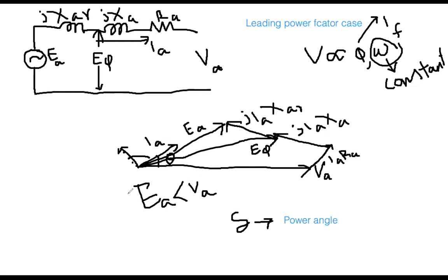So, what is that EA? EA is that internal voltage. And what is the factor? Again, the flux. I am assuming speed is constant. So the main thing is the flux. This means because EA is much less than the VA, the generator needs to produce a small voltage with the expense of a small flux. So this means under excitation. And I got that conclusion when my power factor is leading.